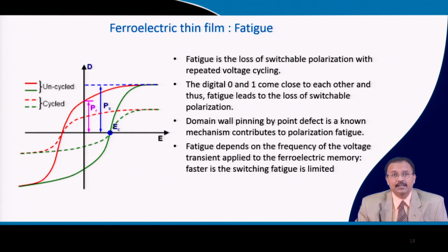So, this is the operation, but if you want to do this read and write several times, then the polarization drops. As you can see, this was the original hysteresis, and after repeated read and write cycles, you can see that the polarization drops down. This is known as fatigue, and this is one of the major defects, and people are yet to solve this puzzle of why exactly fatigue takes place or how to get rid of this fatigue.